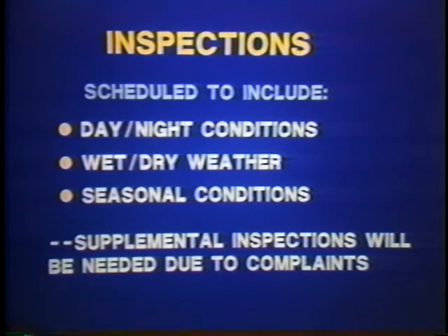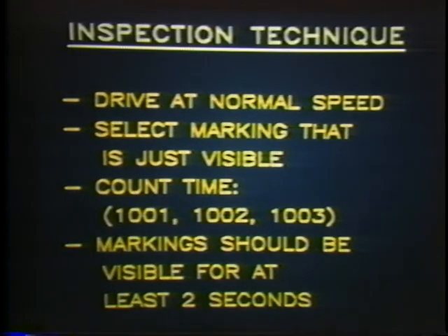Delineation devices should be inspected in all types of conditions to evaluate visibility. Here's a simple procedure to follow to evaluate the reflectivity of markings at night. All markings should be visible for at least 2 seconds in all kinds of conditions.